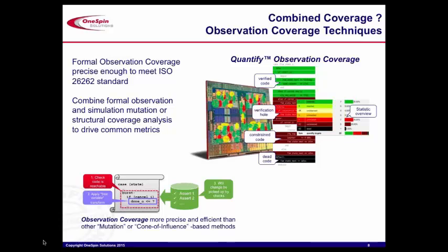And then on the formal side, we can actually apply functional coverage type operations, while also measuring them against the metrics that we need to apply from our test plan. So essentially what we do is we check the code is reachable, we apply a free variable, and then we make sure all the assertions actually create a very full and rigorous functional coverage scenario for this particular design.